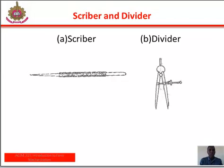Next we have scriber and divider. A scriber is used in making a straight line on metals. It is used in conjunction with the steel rule and tri-square. Dividers are used for making circles or curves. It is useful in transferring measurement. It can also be used for stepping off equal divisions along a line.